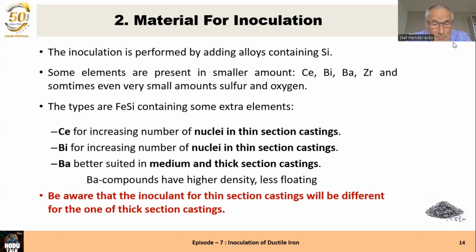One thing in the bottom, you must be aware that inoculant for thin section castings will be different from the one for thick section castings. So if you make thin castings and thick castings, don't think you can do it with one inoculant. You will have to realize that you need more types.